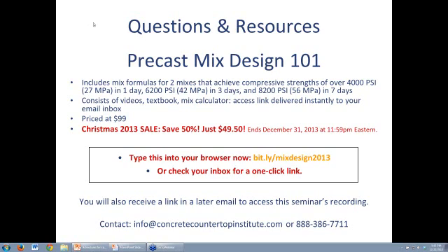If you use warm water to get your concrete up to warm temperatures, let's say if you're talking in Fahrenheit, you get your concrete up to 60 or 65 degrees, so that's what, 15, 18 degrees centigrade, your reaction rate is going to be more normal. Cast your concrete, cover it in plastic like you normally would, and then go to a thrift shop and get some old tarps and blankets and quilts, or get some insulation and cover your concrete. It's going to make its own heat. You just need to trap it. It's not going to be as effective, but it's going to be a whole lot cheaper.